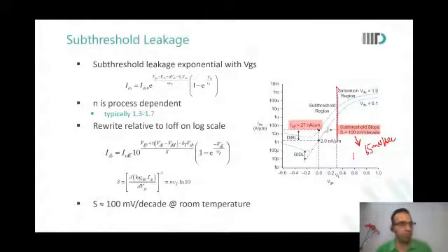I'm not going to ask you these formulae in the exams, and you will not be asked these formulae even in the interviews. What's the difference between VT and VT naught? Capital VT is the KT by Q component. Oh, okay, right. So VT naught is just a subthreshold voltage. VT naught is the threshold voltage at 0 VDS.